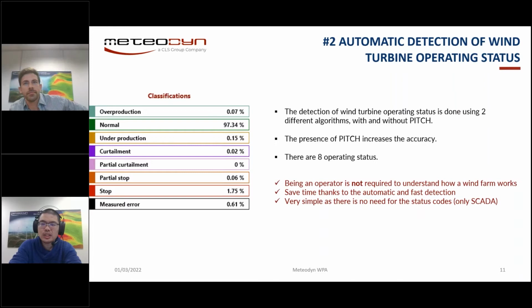The wind sensor gives a value which is lower than the reality. So when we project to the power curve, we see that we have much more output power for this wind speed, but the wind speed is wrong. So there comes the problem.